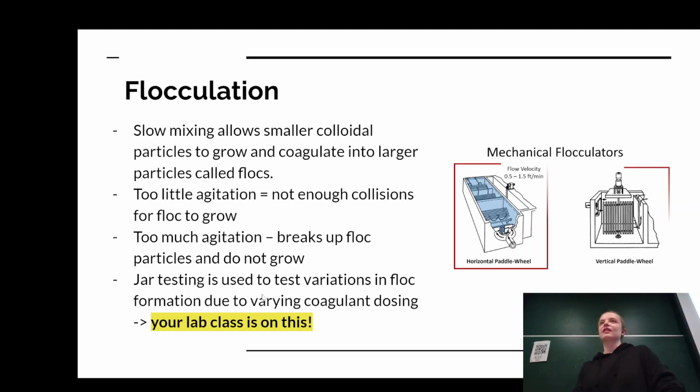Then they do this thing that you do in your lab called jar testing, and they use that to figure out the dosing of the coagulant. And you'll see this in person in like week 7 or 8, I think.